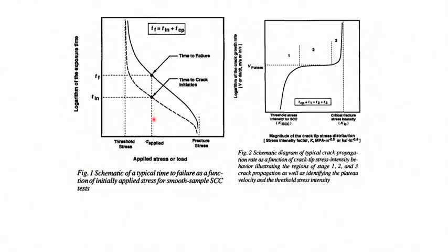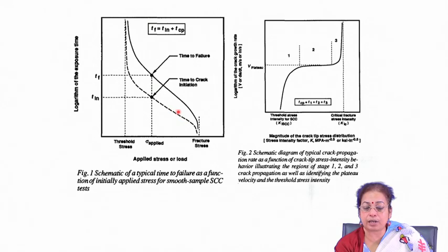So, this is very important. When the stress is quite low, the time required for initiation and the time required for failure are quite high. As you go on increasing the stress, the time gap between crack initiation and crack propagation decreases. And as you go on increasing the stress further, it again decreases to a large extent and finally it fails.